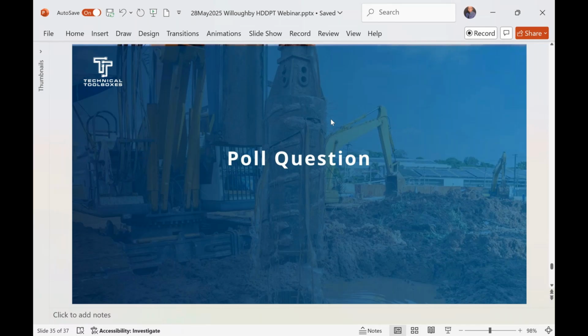Perfect. Okay, another part to this question. Does the tool also perform the drill design for HDPE pipeline? And is there a maximum depth limit for the drill profile of the HDPE pipe? Yes, I didn't show you that, the module I showed you was steel. There's another module in the power tool that does plastic pipe, polyethylene pipe, and it works the same way. It'll do it in any plane you want, and it doesn't have a maximum depth as a number, but it does calculate the loads on that pipe. And again, if you exceeded the allowable external hoop on that, then you get a fail just like you do with the steel.